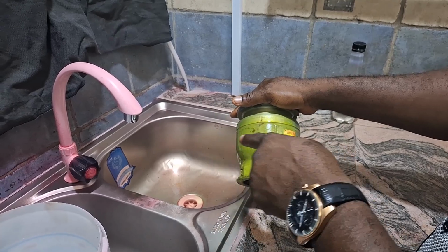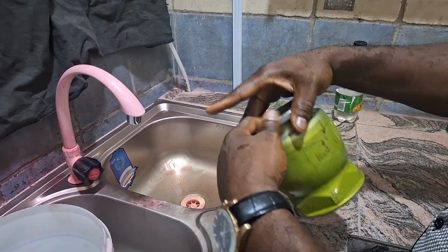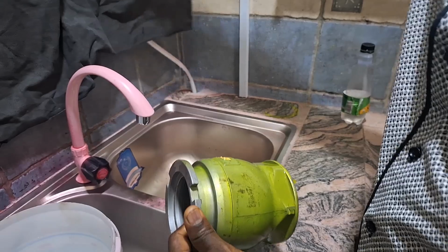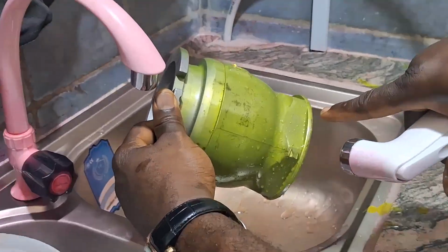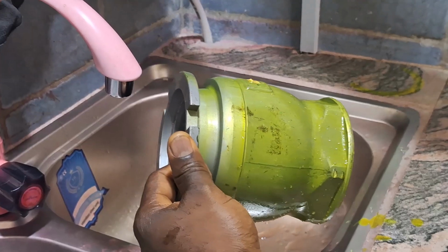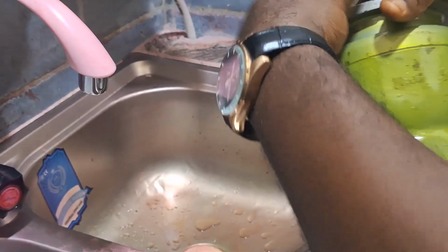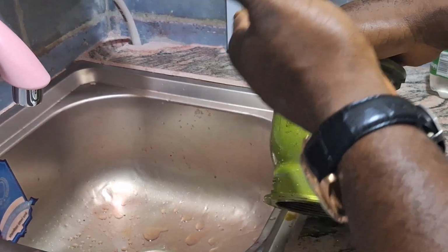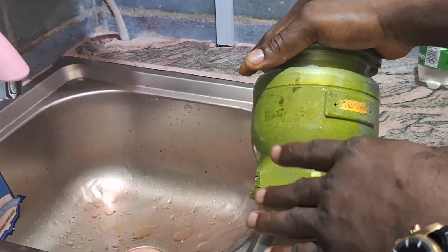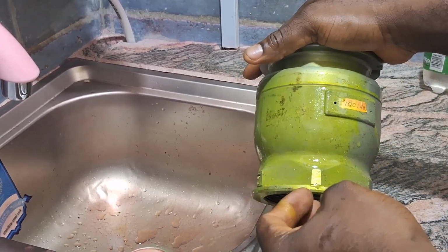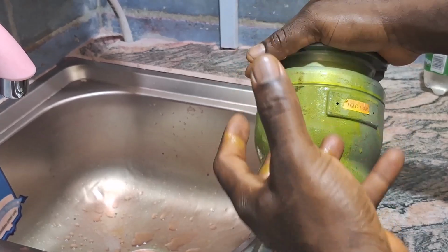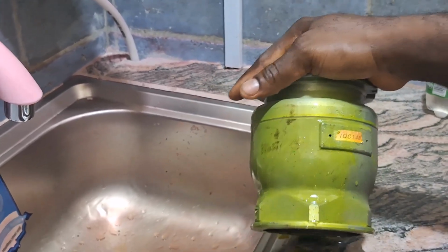But if you just apply water the way this is now, you can see that the water does not take it out. Which means the chemical needs to be emulsified. Emulsification is breaking down of the penetrant into a form that can be removed with water.